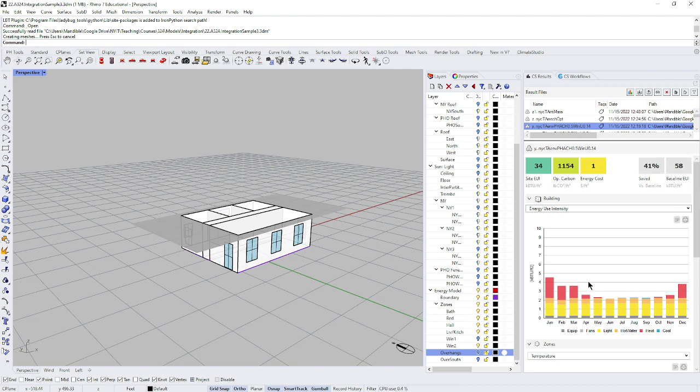And so we get energy use intensity outputs. For example, this chart is telling us the kBTUs per square foot of loss. So this means that we could compare any type of building per square foot and see how they compared. By the way, this is in New York City. We still see that our configuration right now has a fair amount of heating load, but no cooling load. And hot water, we didn't talk about last semester, and lighting, we didn't really talk about.